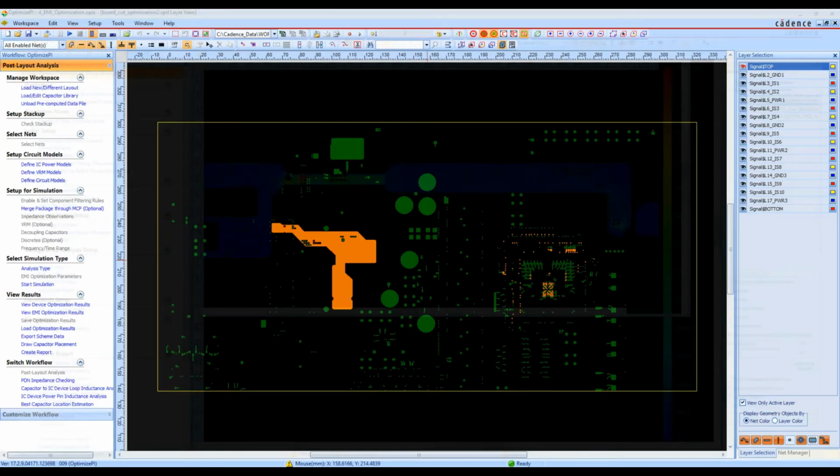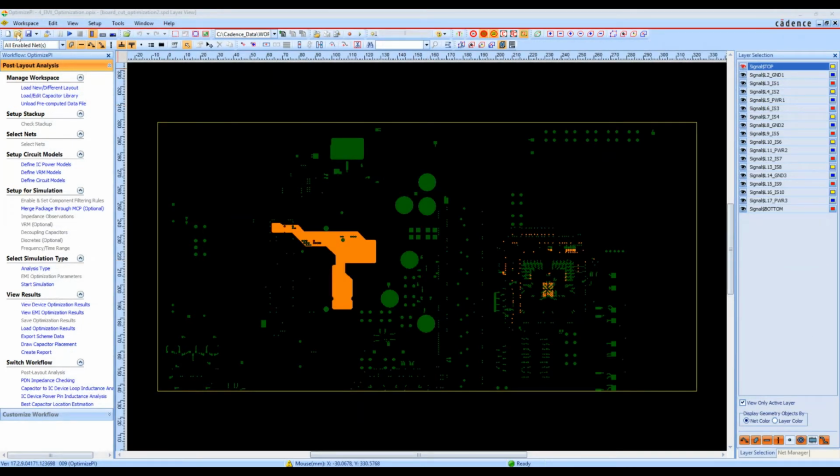For this, we're going to use a different Sigrity tool, and this one we're going to use for the rest of the demonstration today. So we're going to start off and find out if it matters if our power plane resonates. Roger was talking about power planes resonating, and if that's a problem, and how it generates EMI and other bad things we don't want. It can interfere with our signals as well. So we definitely don't want our power plane to resonate if we can avoid it.